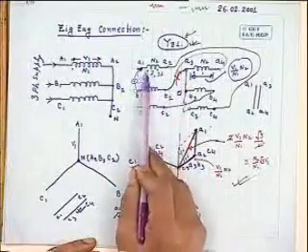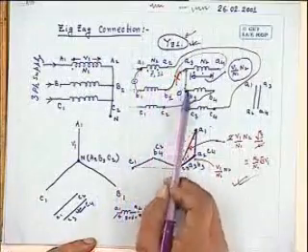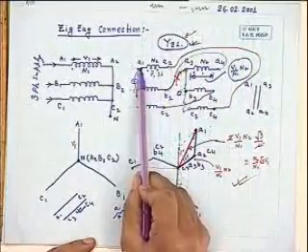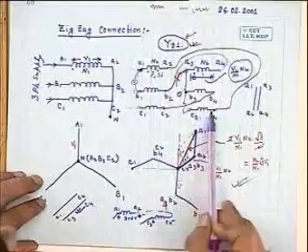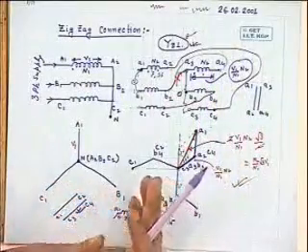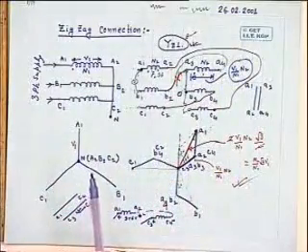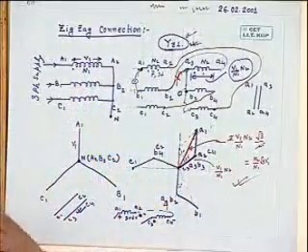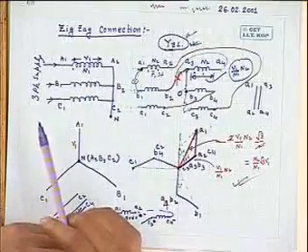Now similarly, you tell me, in this case, if I want to load the transformer by a single phase load, will there be a problem? Can I load that one without the problem faced in the earlier case, because B, C phases were open? In this case it will not be so. Because of what? Suppose you have connected a load between A and this common point and some current let it drive. You find that there is a phase mixing between the common point and one of the terminals here. See, A phase and C phase on the secondary side, both of them will carry current, supplying that load current. Getting or not? This current will have their reflected part in both A and C phase. So there will be a return path from A to C phase.